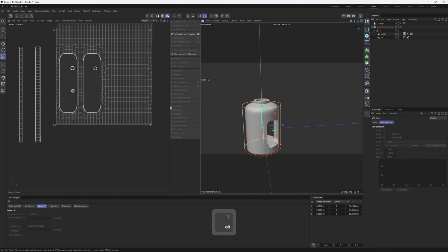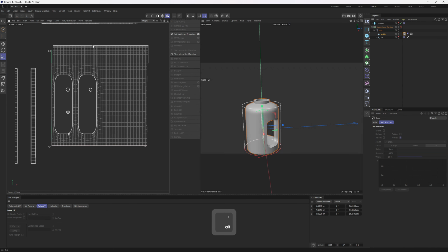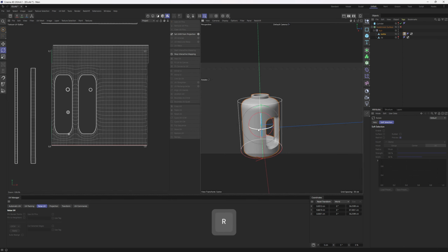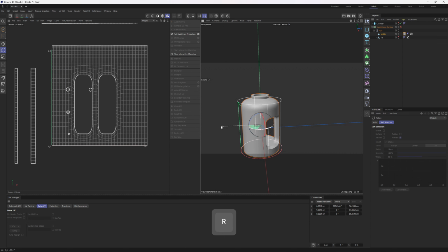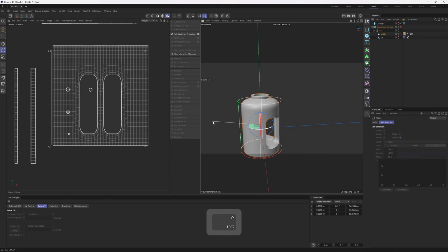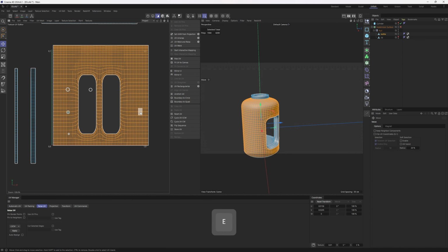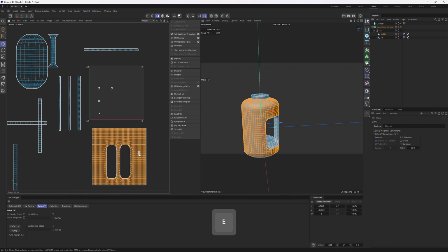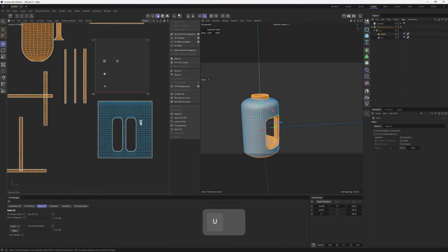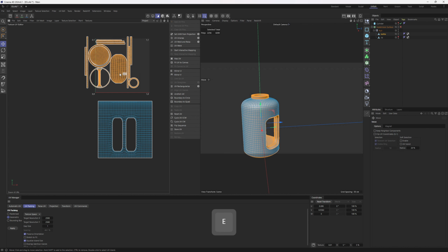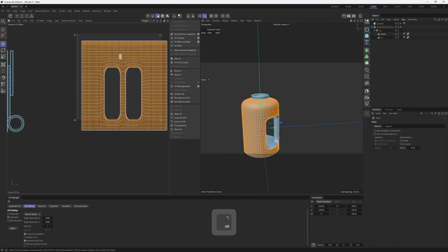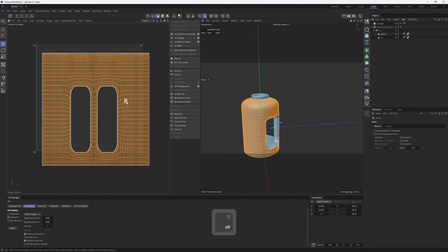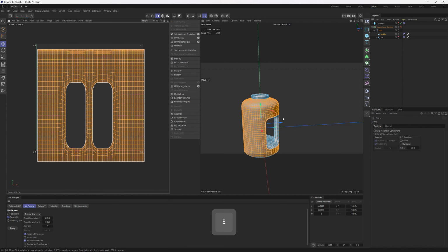Next up, I will rotate it because I want a symmetrical UV island. So I will just rotate it around like 90 degrees. Perfect. Let's move this off. I will hit U and I, then come over to the UV packing and pack this, then move them off again. I want to work on these islands specifically.